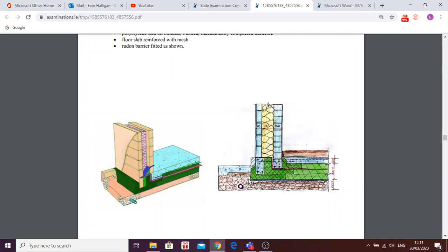Now, you might say, sir, there's no way that insulation will be strong enough to take that kind of weight and that kind of load. Well, EPS 300 is an extremely compact and strong material. This is EPS 300 here, whereas the lighter green over here, where the insulation is spread over a wider area, because it's your floor, obviously, is EPS 100. The same rules apply though. You still have your radon barrier, you still have DPC up here and stuff like that.